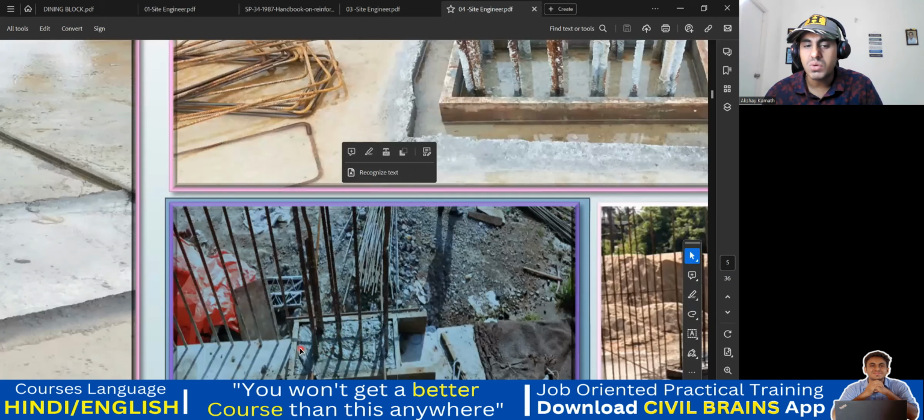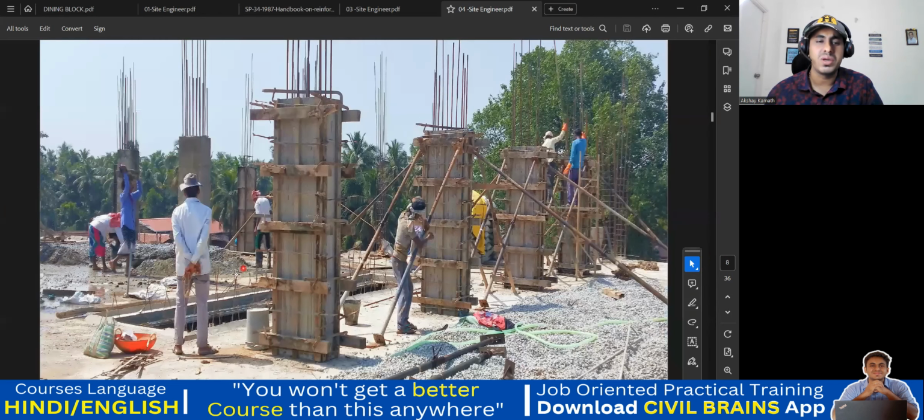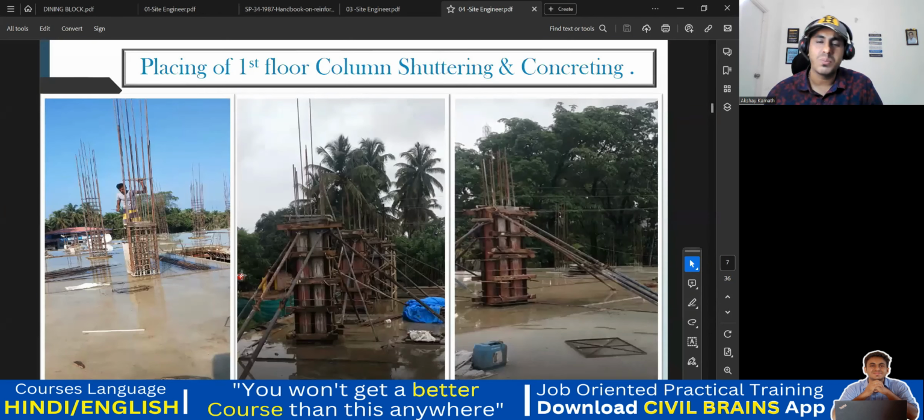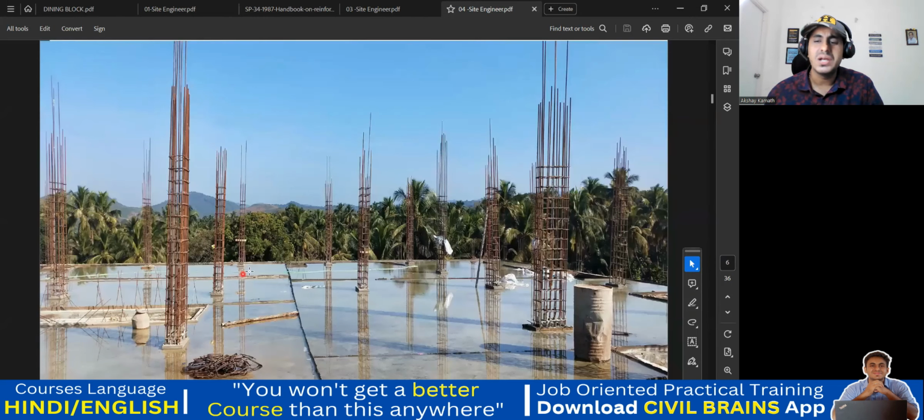So as a result of that, what will happen? A kind of a depression will be created. So this is called a construction joint. Got it? So if you do that, it's well and good. But overall, it doesn't make any difference, as long as you're using your vibrator properly, and if you're properly placing your concrete, if the quality of the concrete is good, it doesn't make any difference.